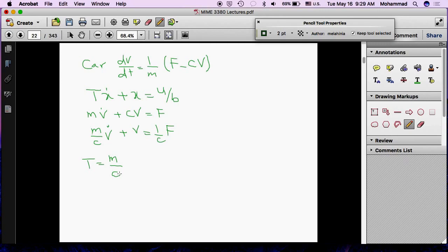What is steady state velocity? Let's calculate that. So we draw a line, separate. If F is known, M is known, and the drag coefficient is known, what is V steady state? What is the method? How do we find V steady state? By doing what? From the model. So dropping the derivative term equal to 0.